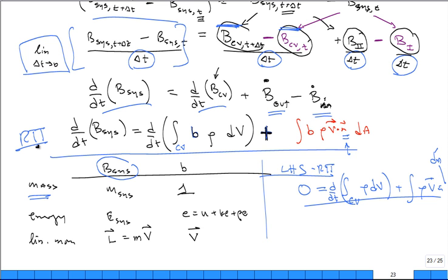Reynolds transport theorem. You can put in the big B as the energy of the system, and lowercase b is the specific energy of the system. We like to think of the three macroscopic forms: internal, kinetic, and potential energy. Now, on the left-hand side, how can you get some increase or decrease in the energy of the system? Heat transfer in.